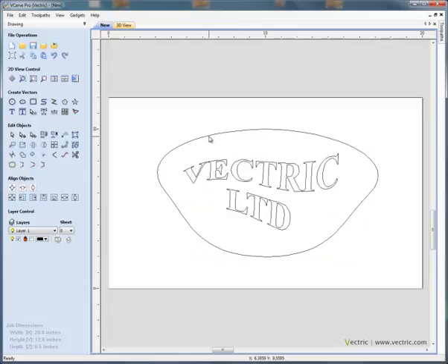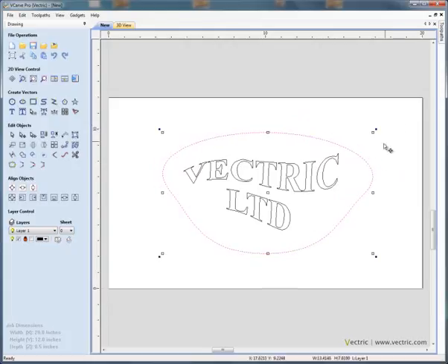So again, click once to select something, click a second time to go into what we call transform mode, where we can change the size of the selection by clicking and dragging. Holding the shift key down scales the object relative to its center point. We can also use the arrow keys on the keypad to nudge things around. You can rotate the selection, so the little black handles in the far corners, you'll notice the cursor allows us to rotate the selection around.